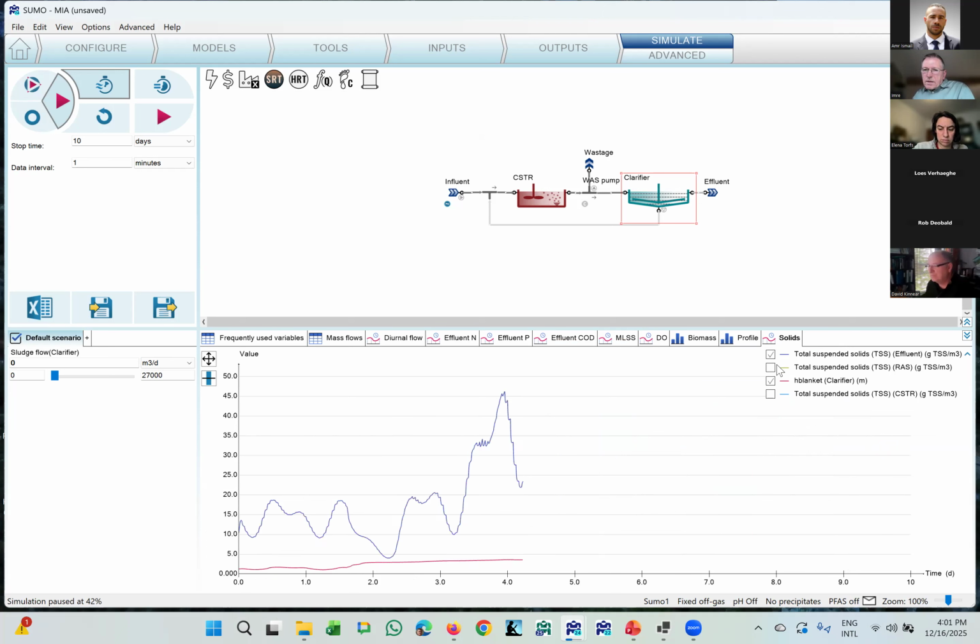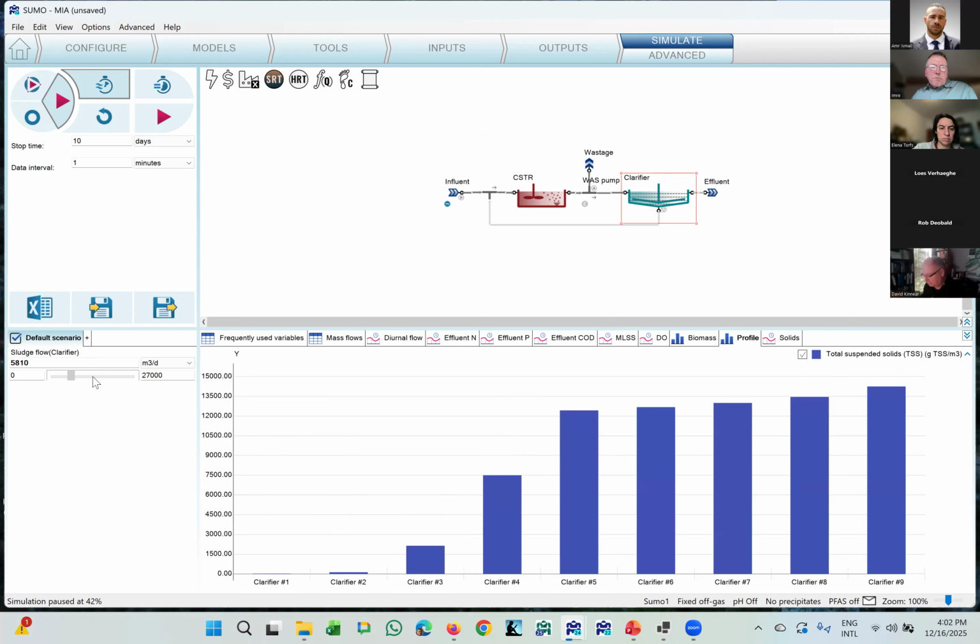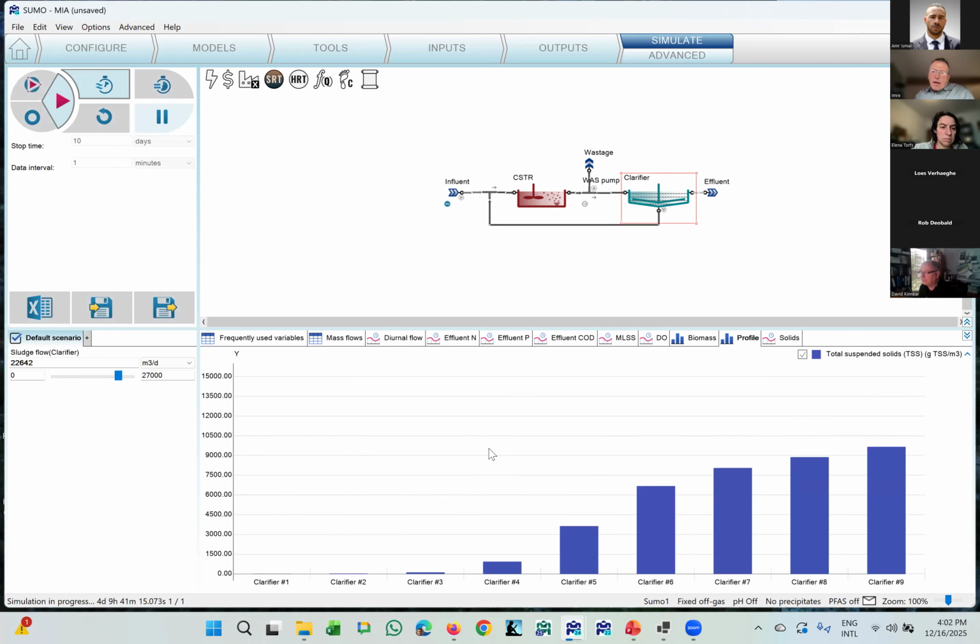So let's take the big numbers off. And that's what the effluent is doing. It's already feeling that there is an increase in the blanket, but it's not a washout yet, because in a washout situation, you will lose hundreds of milligrams in the clarifier. So if I turn this back, we repaired our RAS pump, and continue, then the blanket will fall back to where it was, maybe a meter high, 3 feet or so.